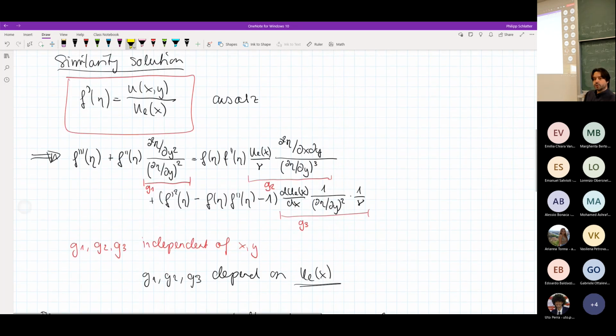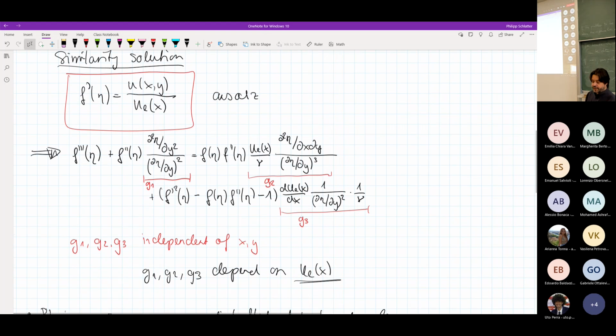Yeah, and then we actually started to solve for the boundary layer profile. We did this with a similarity solution, or a similarity approach, as we did also for the Stokes first problem. I guess we don't need to go through all this derivation again, but the basic idea was that we could write the whole boundary layer equations in terms of this f prime and f double prime, which is our similarity function.